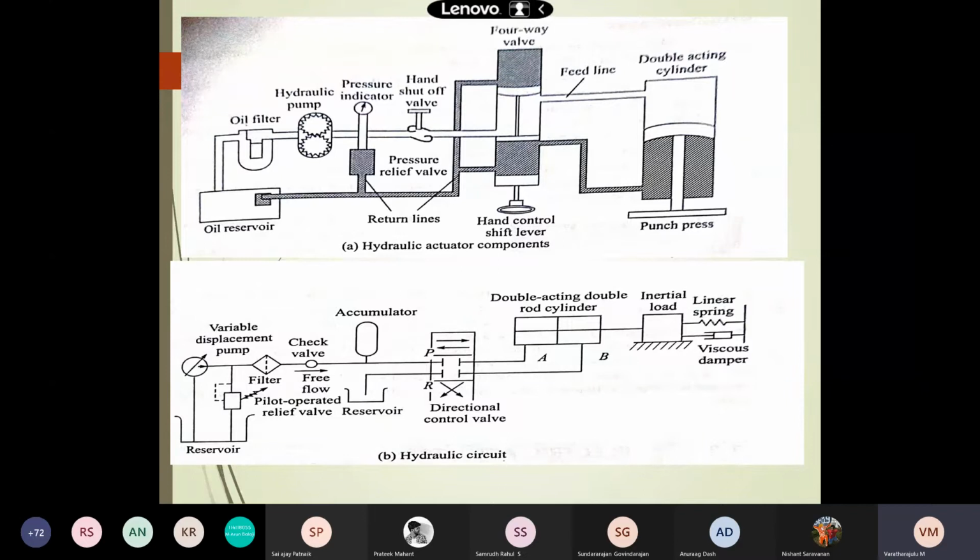Concerning the working principle of this gear pump, on one side we have the oil inlet, and on the other side it sends the oil out, and it sucks. During rotation, of the two gears, one might be connected to the power source and the other might be in idle condition. Once the driving gear rotates, the driven gear is also rotated, but that is an idle gear.